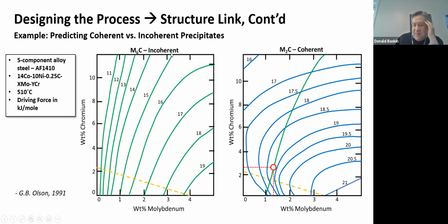Okay, so you see what just happened, I hope. This is a situation where the Steel Research Group found a composition, and by choosing that composition, you've engineered in a certain microstructure. You did this heat treatment, that was your process. You precipitated out what you wanted, that's your structure, that gave you the strength.